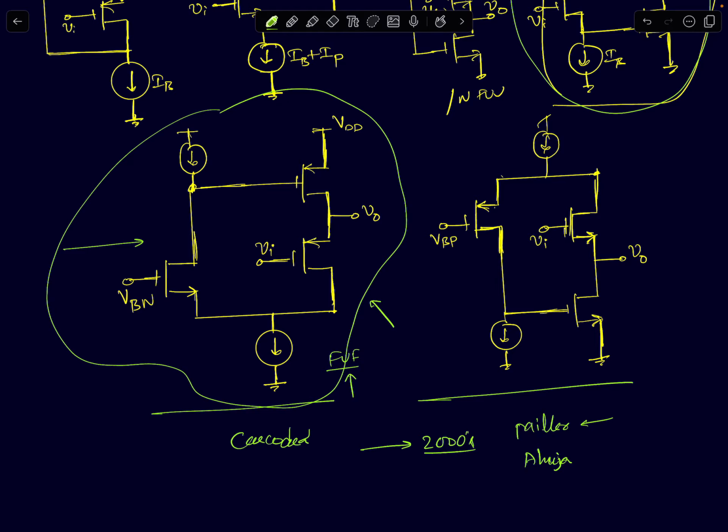Now if you see the current generation of LDOs, in most of the industry, I don't have experience in LDO design for a very long time. I have done LDOs, I think 3 LDOs. Mainly I'm a PLL designer, so the LDOs that I designed were mostly for PLLs. But I have seen how they've evolved for the past at least 15 years. The current generation of LDOs are much simpler, though we use similar concepts of dominant and non-dominant pole compensation. They're very different in terms of how we approach the design. I would say the structures are very different from what we were used to even just 10 years ago.